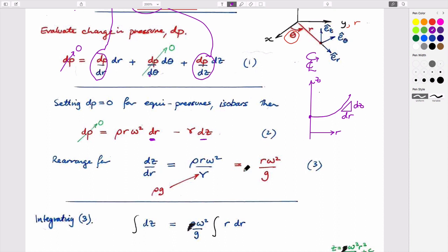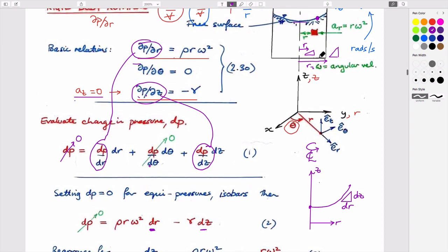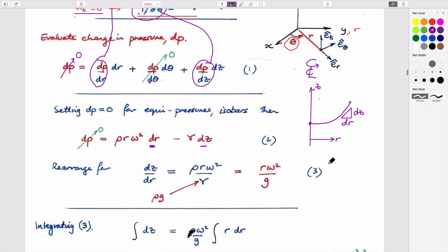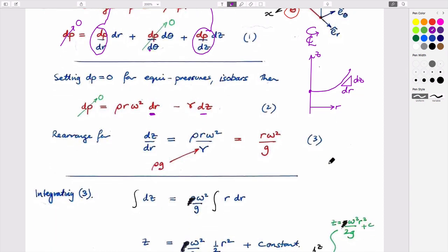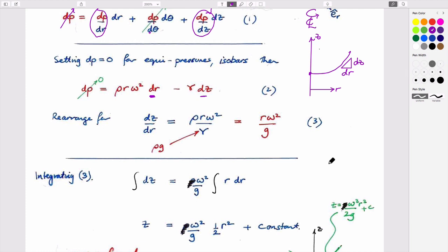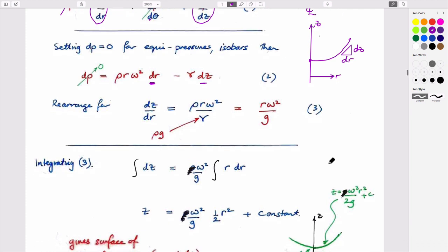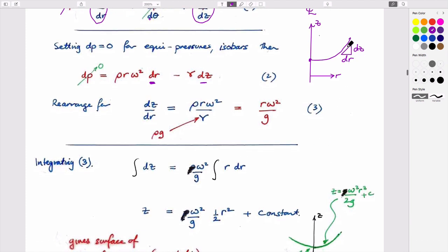As we go progressively farther out, if we go out a unit, then it has to be equal to some magnitude. If we double that, it's actually saying the same thing we kind of suggested here, is that this steepens up. And so that makes it a bit more problematic for us, because now it isn't a constant. It was quite easy to calculate pressure changes with depth because it's a constant. You go double the amount down, the gradient is constant, but the pressure change doubles. And so that means that to be able to calculate the pressure at some point on here, we have to do something like integrating it.